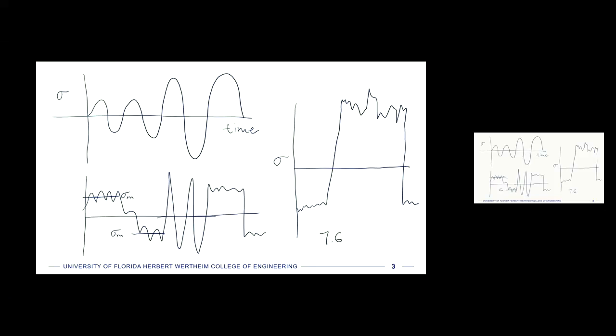And I thought the caption was unique. It says, a quasi-random stress time pattern that might be typical of an operational aircraft during any given mission. So I would assume that when the stress goes up, the aircraft is experiencing a lot of lift, causing in this case a tensile stress, with a mean stress much above 0, and then some fluctuations, stress amplitude around that.